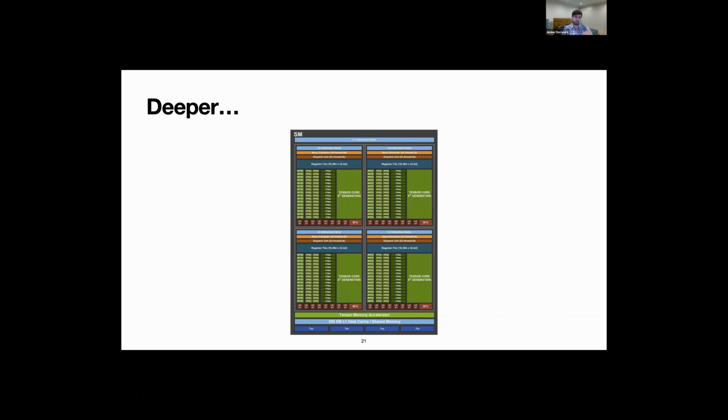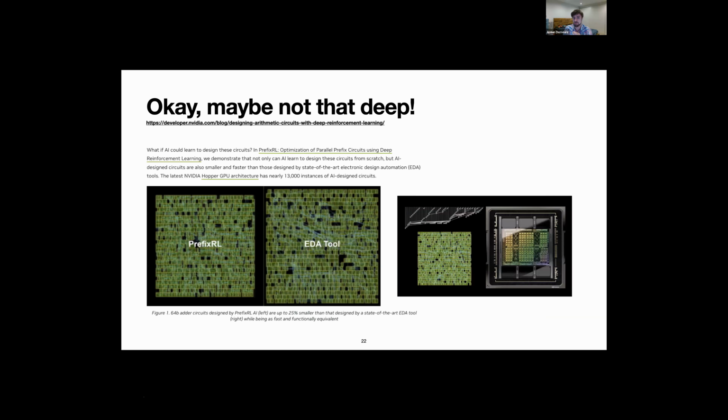There are specific thresholds where if you go from 56 to 64, you actually lose some occupancy, and I think 64 to 72 you don't, and other weird things like that, which are a consequence of very coarse granularity.